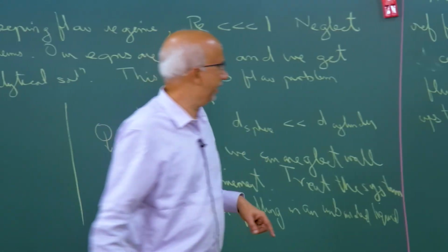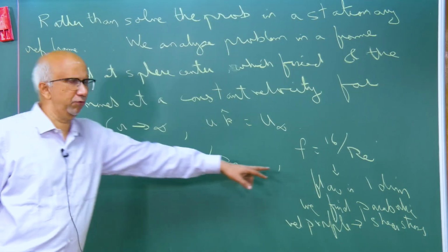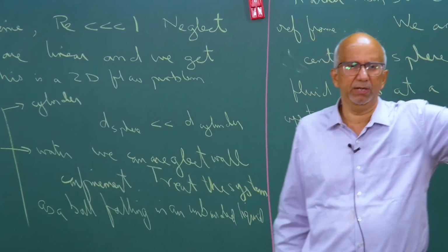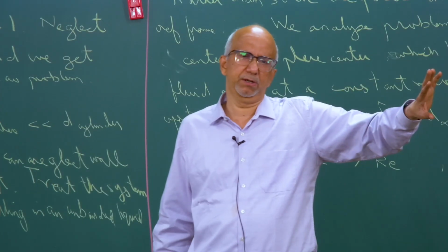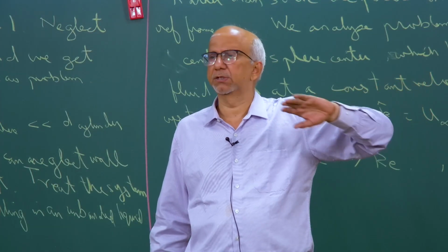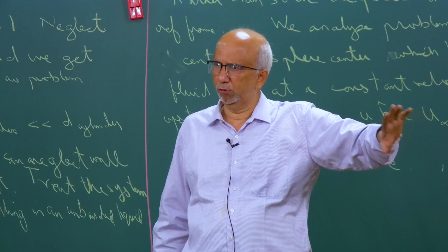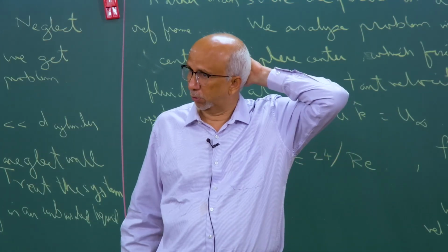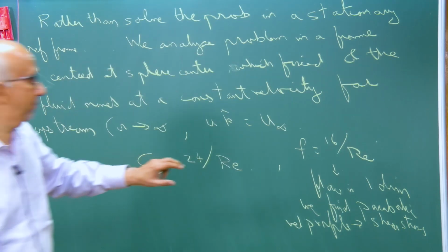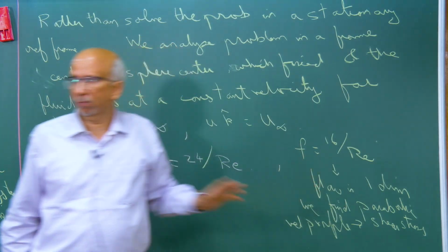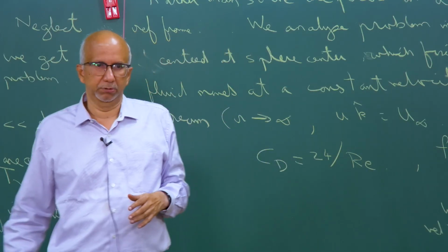In that laminar flow, we really did not assume low Reynolds number, because we assumed fully developed flow, and automatically the inertial terms dropped out. So, in some sense, this is a one dimensional creeping flow problem, because the inertial terms did not contribute.